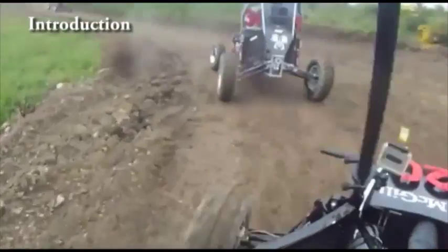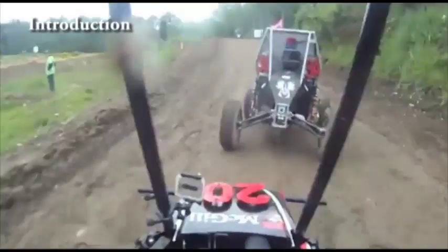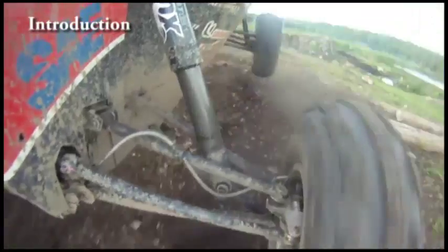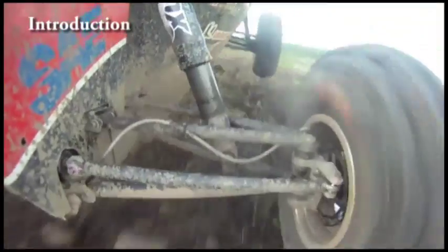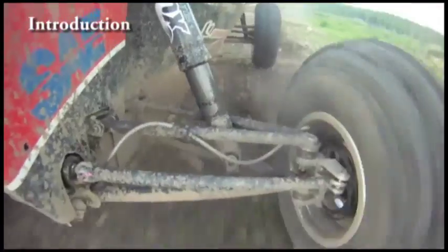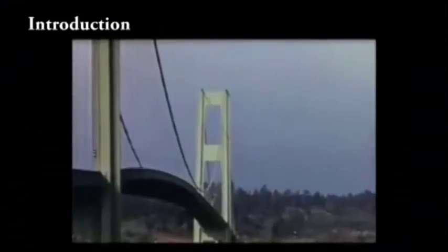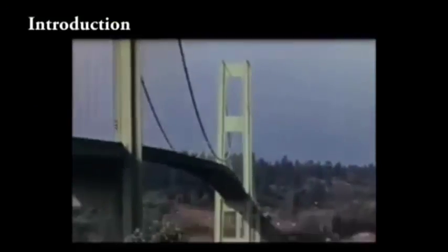Introduction. Free vibrations happen in many structures, where the structure vibrates at its natural frequency. Forced vibrations may occur where an external force causes the structure to vibrate at any frequency, including the natural frequency of the structure. When the forced vibration frequency equals the natural frequency, the structure will resonate at a potentially dangerous amplitude and might damage the structure.